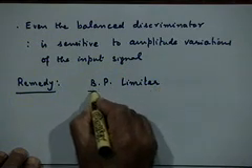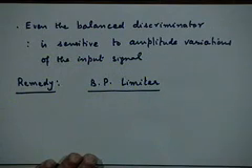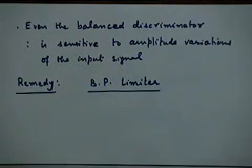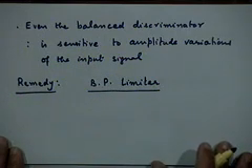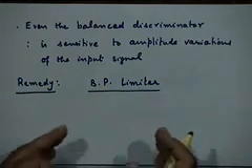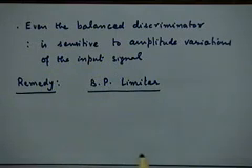And basically I gave you an intuitive feel for how a band pass limiter works and what it does. Let us develop a slightly better understanding of that to polish off our discussion on FM demodulation, because this is an almost essential component of the FM demodulator. Before you pass the FM signal into the FM demodulator or into the balanced discriminator, you must pass it through a band pass limiter, right.